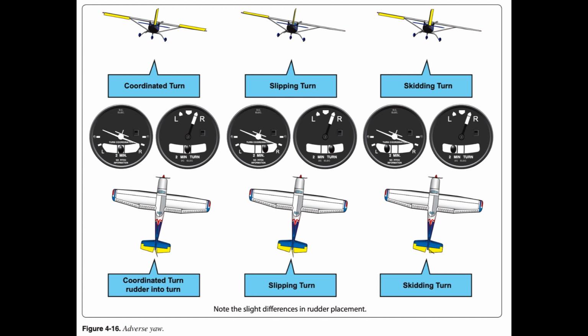The specified load may be expected in terms of aerodynamic forces, as in turns. In level flight in undisturbed air, the wings are supporting not only the weight of the aircraft, but centrifugal force as well. As the bank steepens, the horizontal lift component increases, centrifugal force increases, and the load factor increases.